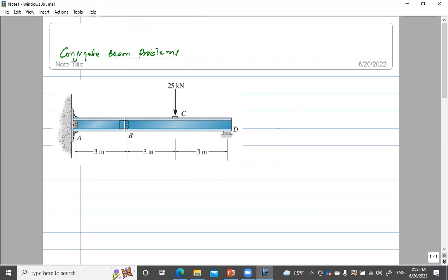So now we already have a bending moment diagram, so I can skip that step. The M over EI diagram: this is 37.5, right? Minus 37.5 over EI. Correct? Okay, now let us convert.